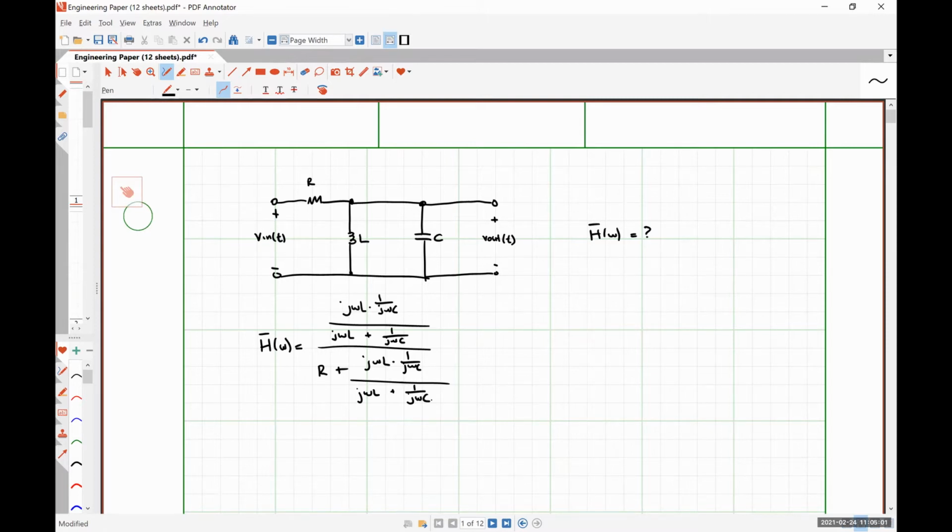So it would be a simple question like this where I give you some odd looking little filter circuit with some combination of resistors, capacitors, and inductors, and then you apply voltage division and tell me effectively what the ratio of the resistances is that will give you the transfer function H of omega, where, just to be super clear, this is determined by taking the phasor output voltage as a function of omega and dividing it by the phasor input voltage, where we assume that Vin of omega is just 1 angle 0 to make our lives easier.